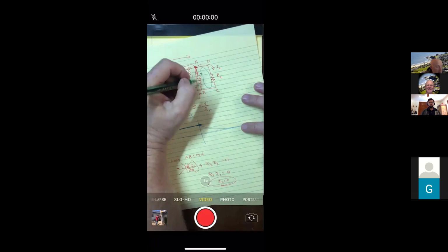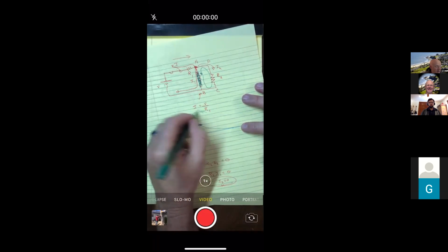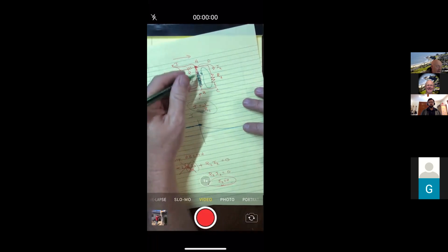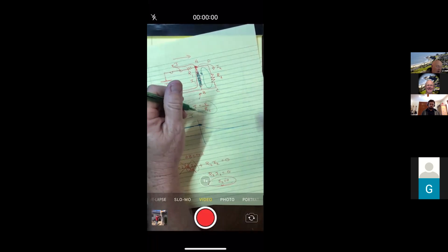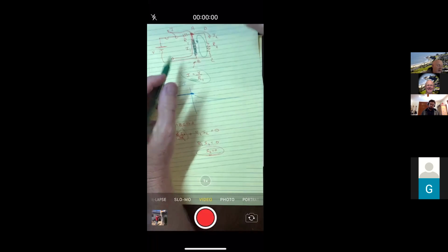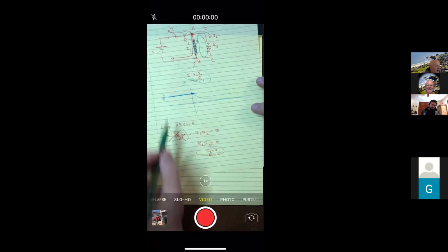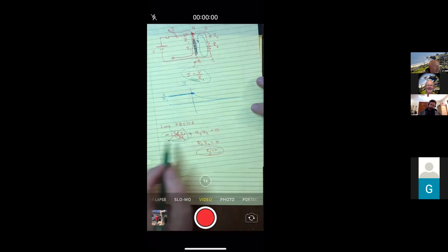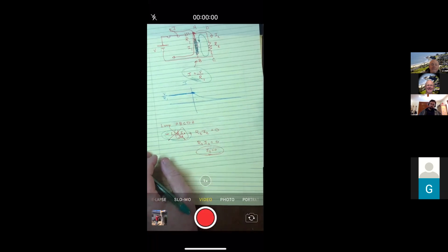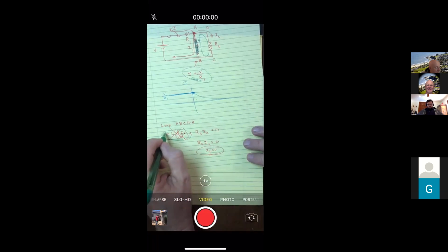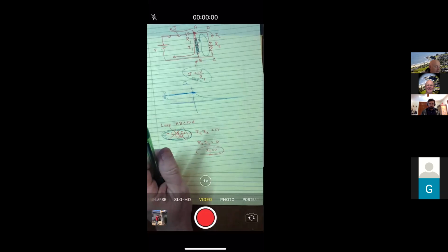If I were to draw in green the magnetic field, it would be huge because of this current. But it is also stabilized at a constant current. And so it is no longer changing, and no longer changing means we no longer have a back EMF. So that's only for a very, very extremely short period of time as that current just begins to flow through that you have that back EMF.